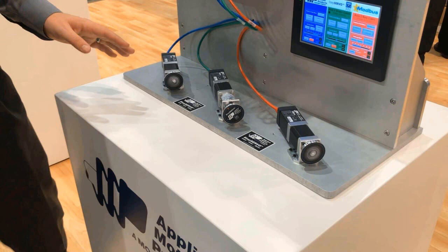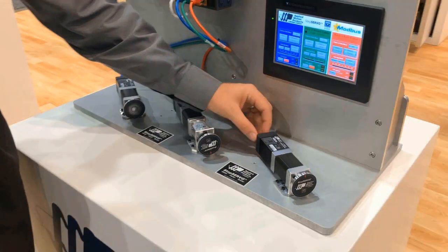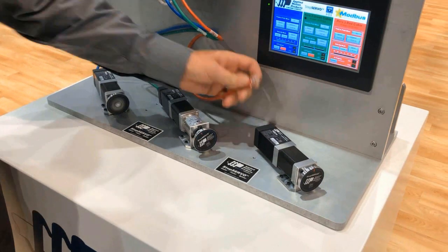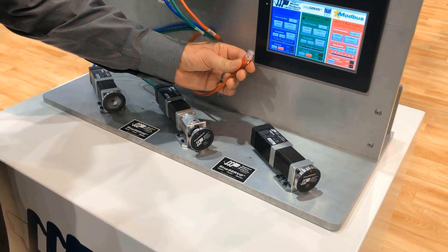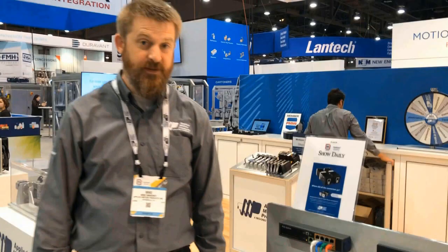So when he plugs it back in, if it doesn't occur to you immediately, he's hot plugging the motor. So he's not turning the Ethernet switch off first to plug the motor in. And this is, again, another very user-friendly, easy to use thing about PoE: you can hot plug the motors with the Ethernet cables.